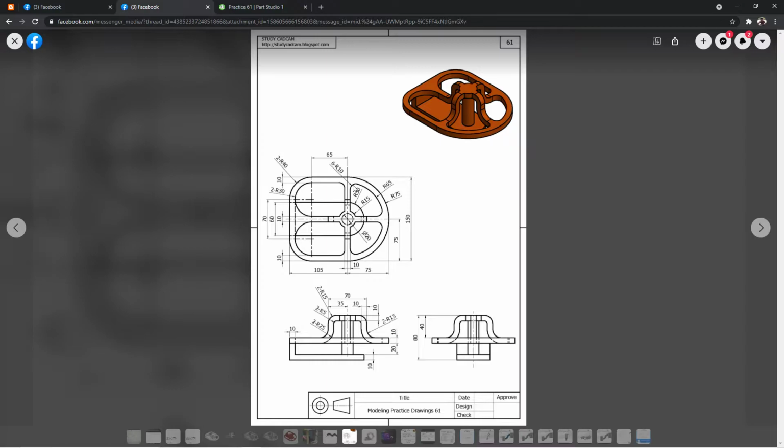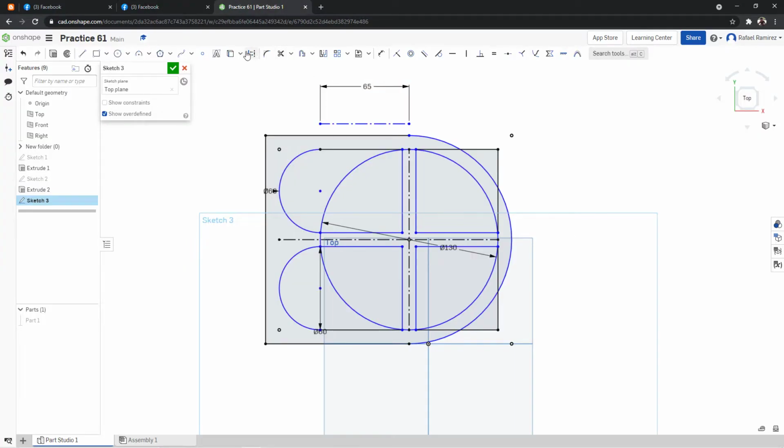One, two, three, four, five, six, seven. Oh yeah, that's six. So I'm gonna use sketch fillet on that point. I'm gonna indicate this point also, that point also, and this point, I'm gonna indicate a radius of 10. Wait, I gotta just double check that one. 10.